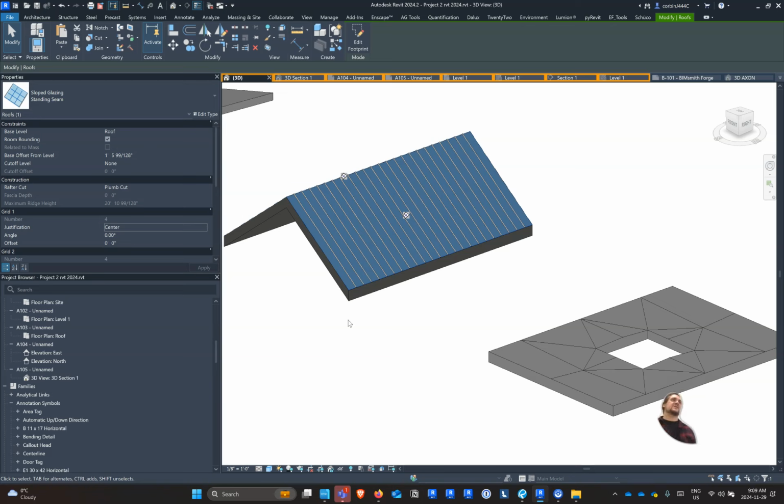It takes a little bit of the guesswork out of it, especially since you're kind of just learning about layers and materials. I think it's a great tool to start to use to build your walls. My recommendation for you is never use anything generic. So never use generic floors, never use generic walls, never use generic roofs. Always try to have a specific wall or roof type.